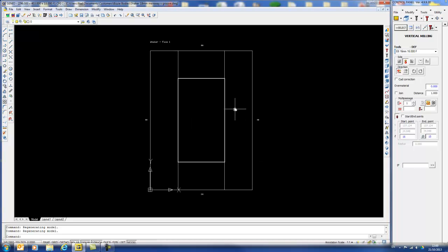So we could save those parametric shapes, but if it's just to do with this drawing, it's good enough on there. So if we go now, let's say we want to machine the outside, let's say we're going to nest it, so we'll go for cut, select your cutter, outside, say clockwise, the board thickness, how many passes, all as normal, go to select, pick on the outside geometry. That has now put the tool up there. Obviously we could add lead in, lead out, etc.